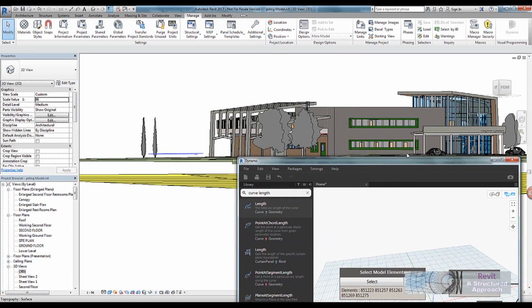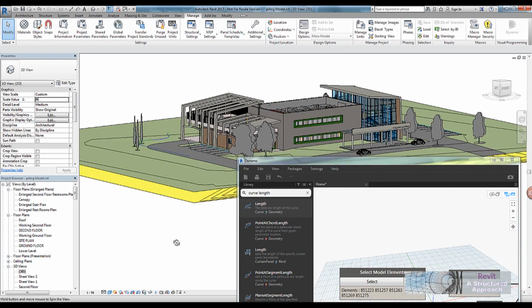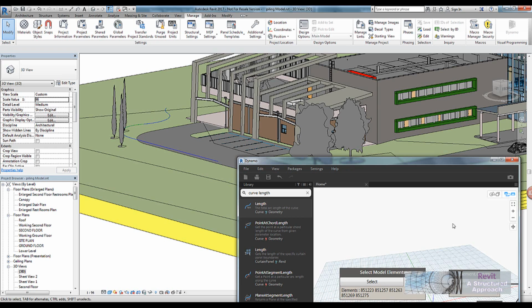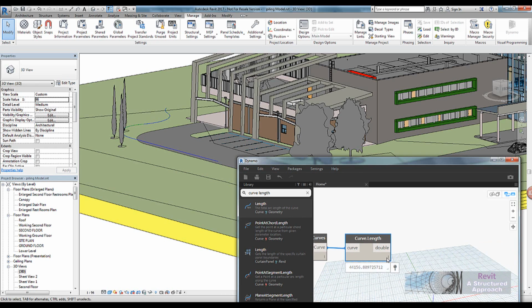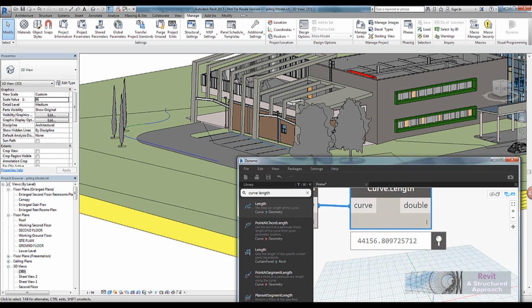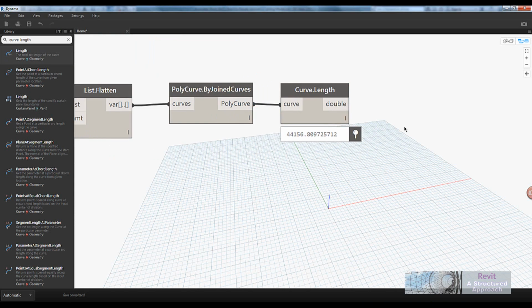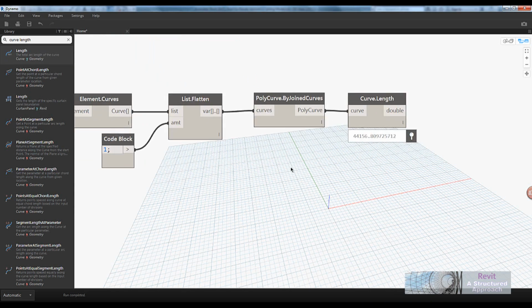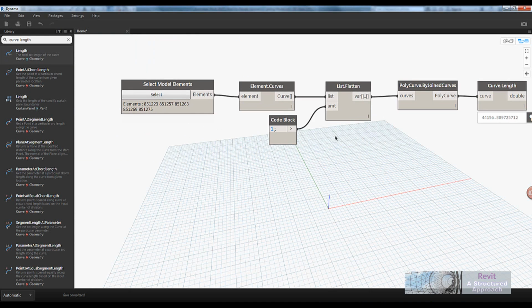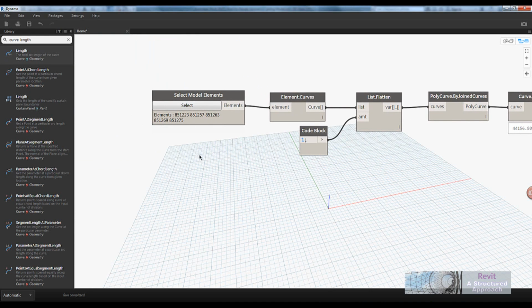Now, of course, the whole thing in Dynamo is completely live. So if I start to make some changes to the geometry, let's just turn the data preview window on, and we'll select this here. You can see instantly the curve value changed there. Let's put it back into 20 meters. Yeah, and there's a change. So that's the nice thing with Dynamo. It's constantly connected into its application, which in this case is Revit. Okay, that's good. So let's move forward a little bit more.